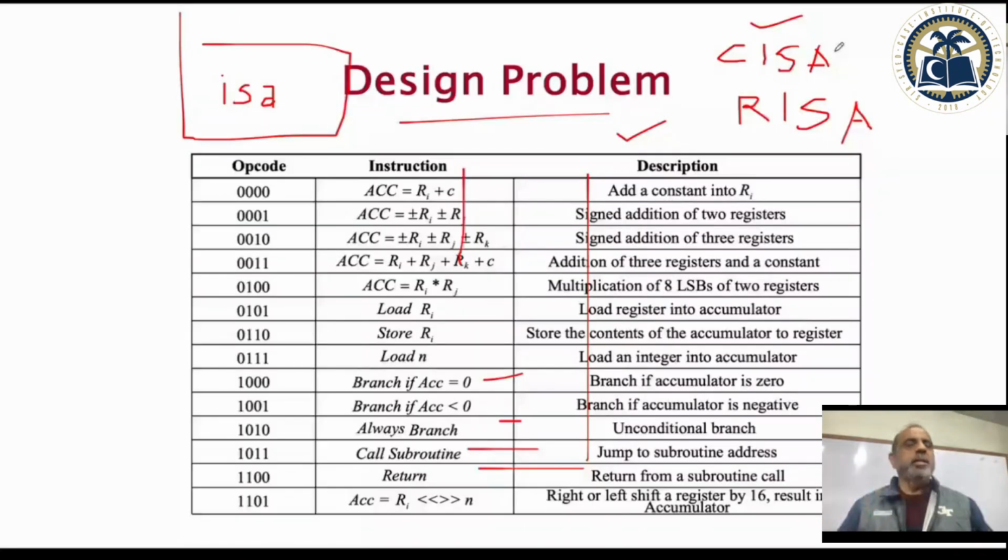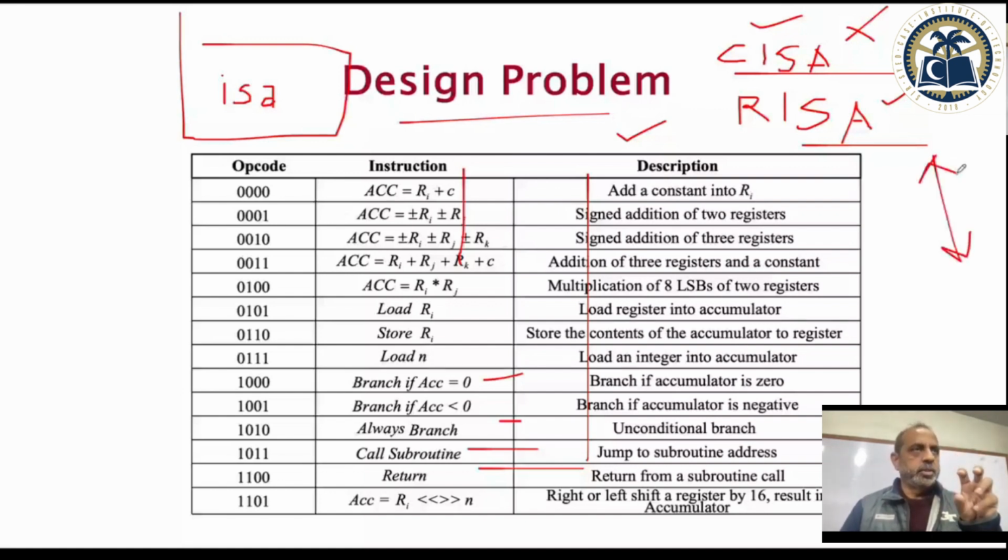So people started thinking about why to go for a CISC architecture. Why not have a very simple architecture which can just do addition, subtraction, multiplication, always register based. And if I have to do a cosine, which perhaps I'll do once in a moonlight, once in 1,000,000,000 times, I'll break it down into simple instructions and execute it. So all general purpose processors would prefer not to be CISC.